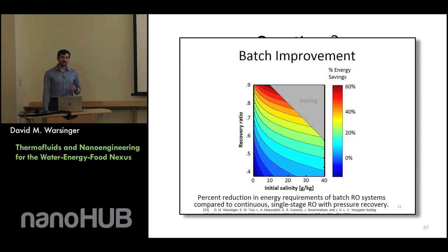We were actually about to do a study showing that the batch reverse osmosis system needs less treatment of biological matter because the cycling salinity should be biocidal. And Sina has been working on that. We got some membranes from a similar process that wasn't designed for energy efficiency, but was cycling the salinity. And we couldn't get any live bacteria from the membrane.